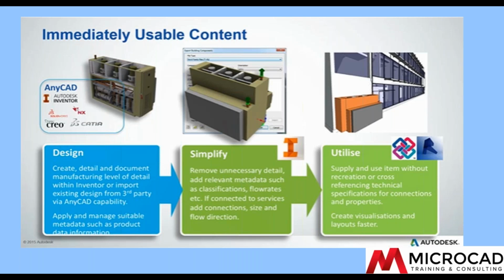Any design created in Inventor is usable by Revit. Typically, you would simplify the model because the architect doesn't need the same level of detail the manufacturer does, then parameterize the model to make it easy to use, and output a Revit family.